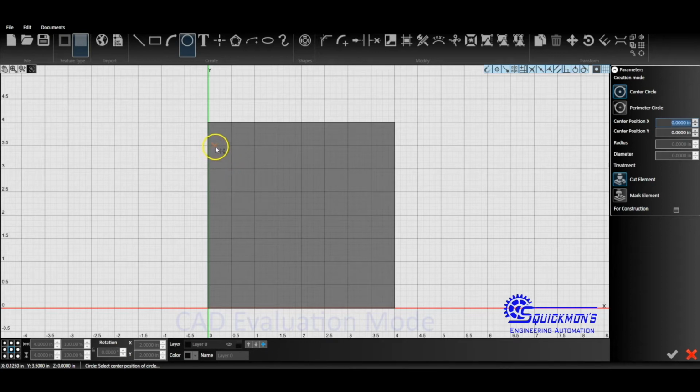So this would be a major grid line where we're seeing this dark square line. All these smaller ones are called minor grid lines. So we're going to go ahead and go right here to our ½ inch in from one side and ½ inch in from the other. We're going to click, and now what we're going to do is notice on the right hand side of the menu we're selected as radius.